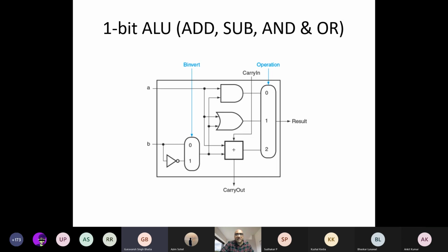The adder will perform addition normally. The same adder, in case of 2's complement notation, can carry out subtraction in the form of addition. For that, the second input, whichever needs to be subtracted, has to be inverted and then added. Along with that, the 1 also has to be added, right? So when you're performing subtraction, it also supports addition if required.